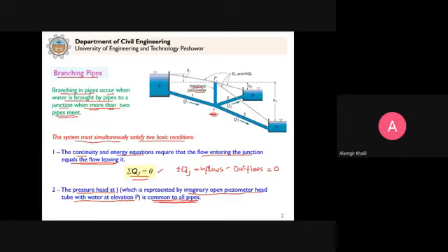The 3 pipes meet at A, the entrance where the flow enters into the 3 pipes, and then they discharge again at some downward point B. If you remember, there was one pipe, then another pipe, and then a third pipe, and then they meet again at some downward point B. And then at this point we have the piezometer, and at this point we have the piezometer, and the difference of level was represented by the head loss.